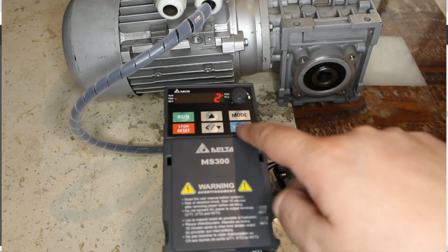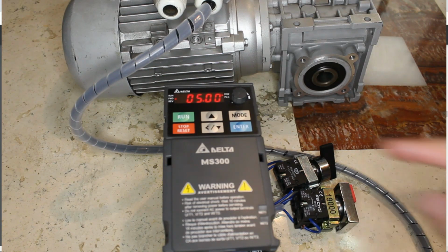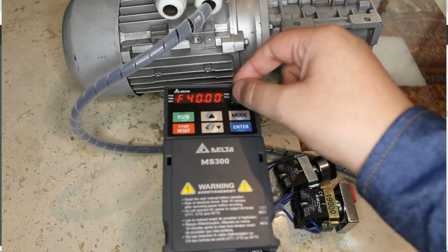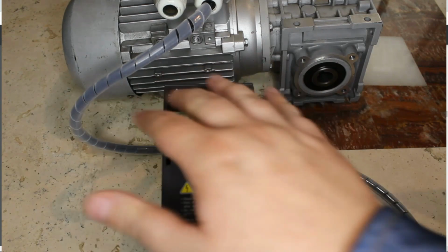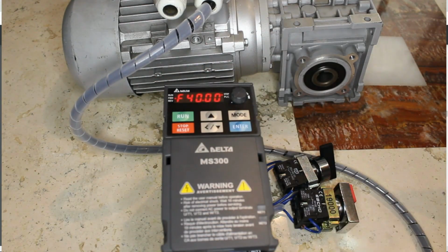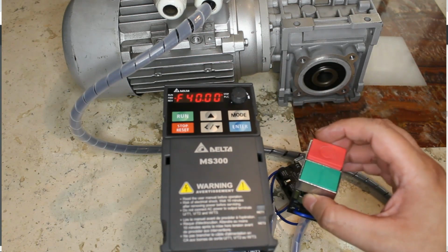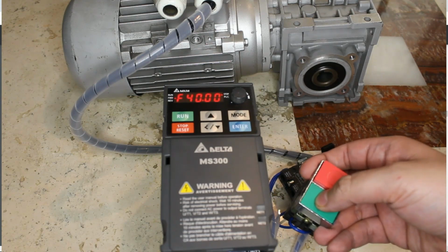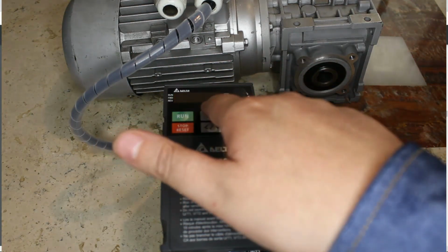So then how does this work? I'm going to hit enter here, and first I'm going to choose the static tuning. It's telling me by default it's not going to listen to my speed part or my velocity part, so it's not going to listen to my button box or my keyboard, because then it's going to be for external digital input. So what's going to happen here? I need to press my start button only. And here my drive is indicating that it's tuning.